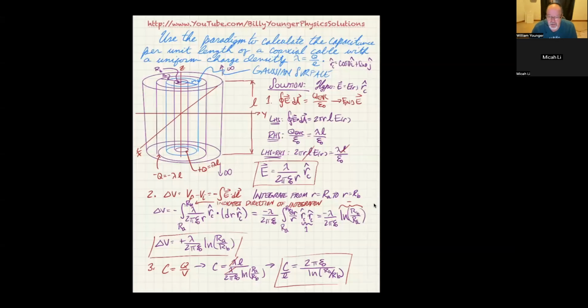In my drawing, I made the radius of the inner wire, the smaller one, RB. So that's a smaller number than RA. And when you take the natural log of any number less than 1, you automatically get a negative. Oh, I got you. Does that make sense? Yeah, that makes sense. And then they're both negatives and they cancel out, so it's a positive capacitance. Exactly.